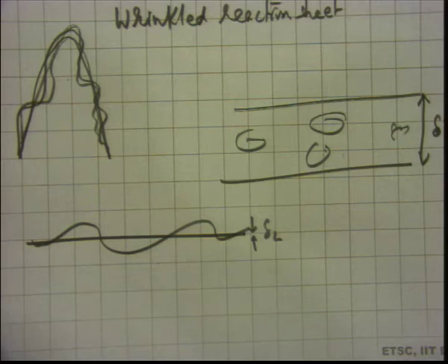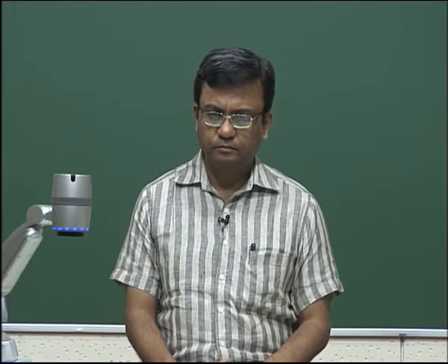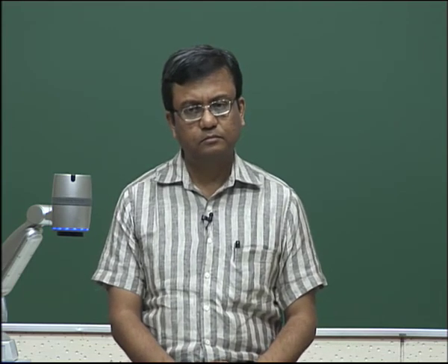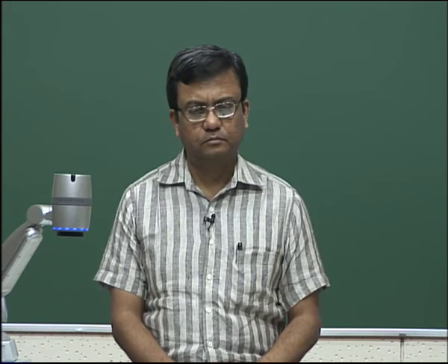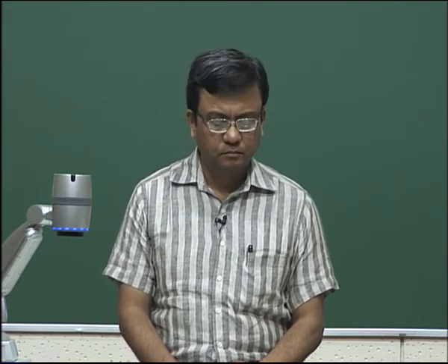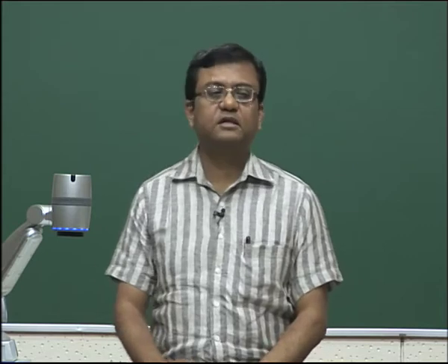Yeah. Can we interpret it like this? When the reaction rate is small, the heat generation will be less. The temperature gradient from the flame to the inward side will be less. So, the flame thickness will be high, because its reaction is less. So, it will try to have more zone for generation of heat and reaction purpose. That's why. Yeah. So, there is a temperature, correct.